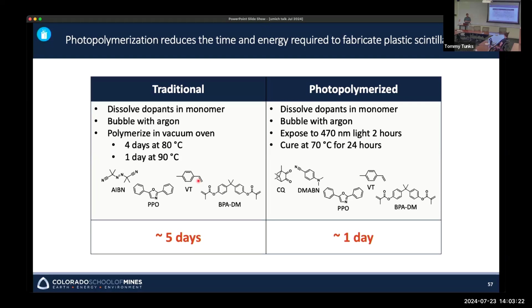Oh, to go back and check for unpolymerized? Yeah, no, we haven't done that. It's a good idea. We should take those parts and do one of those leaching studies to see. Yeah, that'd be interesting. I think the additive manufacturing would be beneficial for that, because it's a pretty high flux of photons in that additive system. It's way more than what we're doing. Cool. I was thinking maybe it's also a penetration issue with the photons. Yeah, because again, a lot of the dopants in there are stealing photons away from what they're meant to be doing in our system.